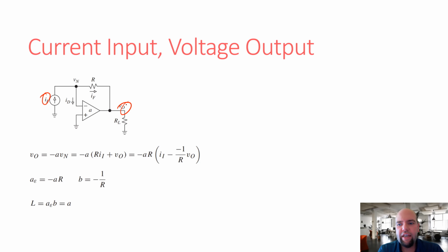Well, the best way I've found is to model the amplifier with a substitute circuit, with an equivalent circuit. The thing to point out though is we cannot simply assume that Vn is equal to 0. If we're normally doing an ideal assumption analysis, then we can just say Vn is equal to 0. That's not what we're doing. So we still have to represent Vn as a variable. We still have to deal with it as a variable. So let's build our equivalent circuit here.